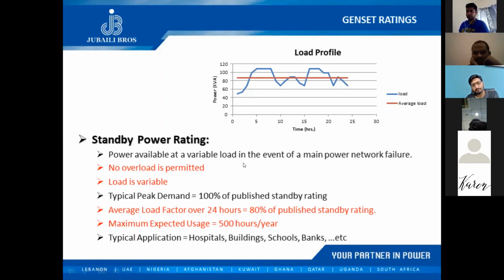Nadim is asking, is it only for 2 years for standby applications? Yes, Nadim. For standby applications, it's 2 years with a limit on the number of running hours. The number of running hours should not exceed 500 hours per year. No, the warranty is not only valid for UAE.